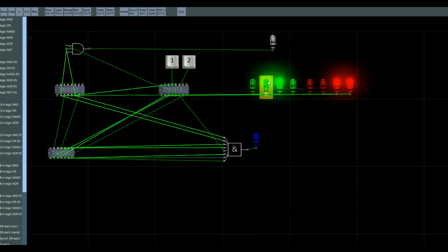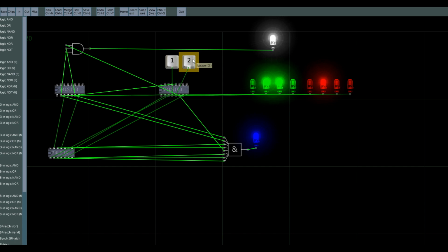So at the moment we've got these bits on and these bits, and we're going to increment by 1, and we've now got a blue lamp on, a white lamp on. So we've hit our value, so we know we're at 100, and we've done it in 2 different ways, which is fine. The cheaper way is obviously we didn't need to use this 04 chip, and we didn't need to use an 8-bit AND, which is probably more expensive than a 3-bit AND. All we needed was a 3-bit AND.